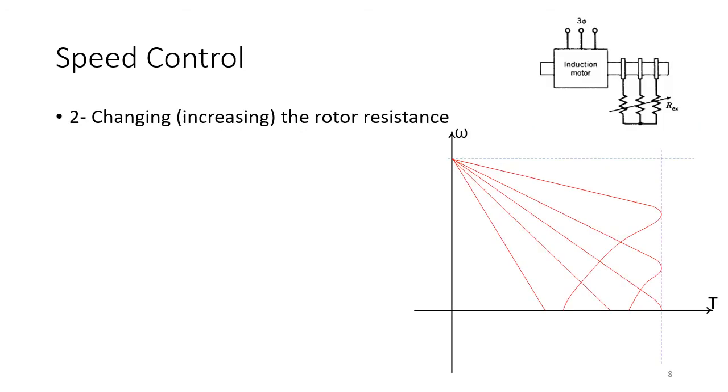Seems so. The other solution is already known to us. It's increasing the rotor resistance. As I said previously, we have these slip rings here, and then we increase the external resistance.